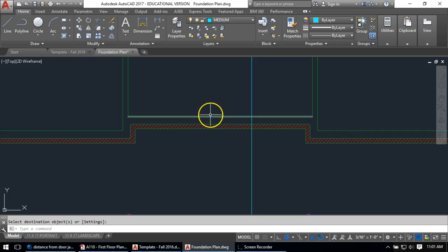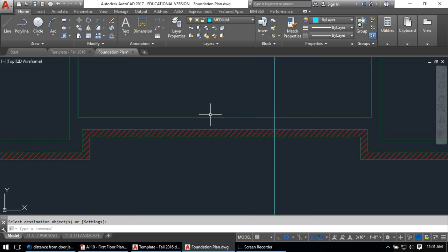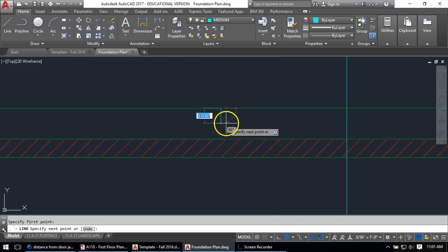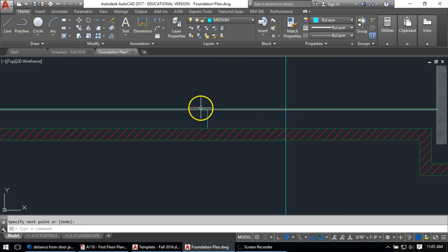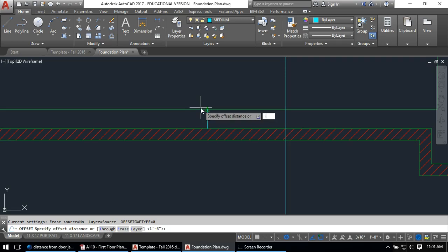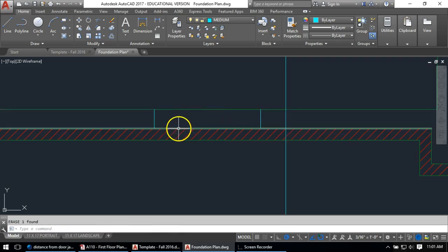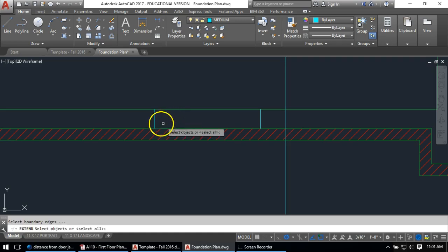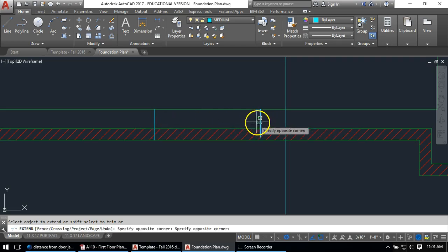We can see it's in the center point. The dimensions are the same. So we know there's a center point here. So I'm going to strike a line using my midpoint. The first door is 36 inches wide, or 3 feet. So I can go 1'6" to each side. Erase at this middle point. This is my wall. It's of course going to come through the brick. I should have just drawn my line all the way through, but I can extend my line down using the extend command at this point if I want to as well. And I can trim out all the stuff on the inside.